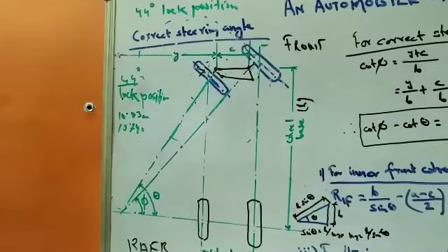It is different for various cars, from the Premier Padmini to the Hindustan Ambassador. The turning circle on the right hand is taken as 10.83 meters, and on the left hand it is taken as 10.7 meters. This is the turning diameter, basically. For the Tata bus LP 1210E, the turning circle diameter is 21.6 meters.